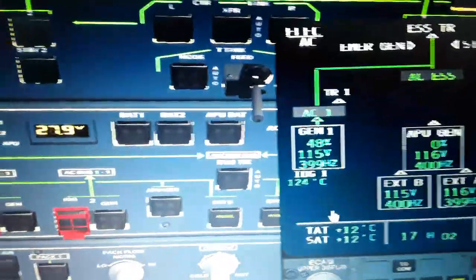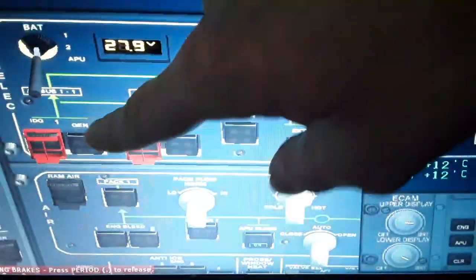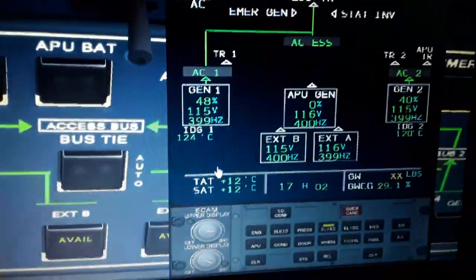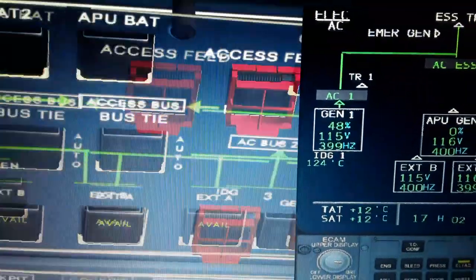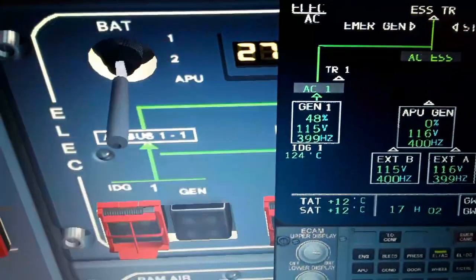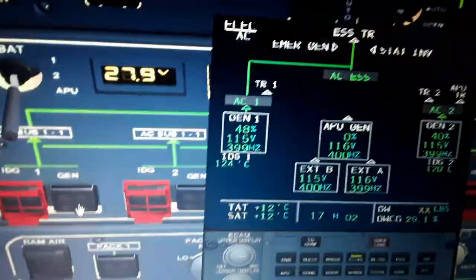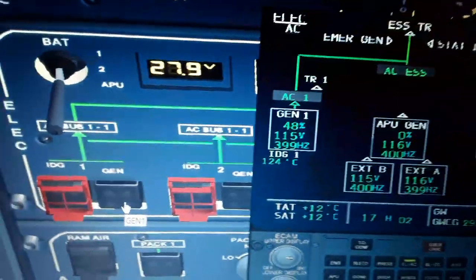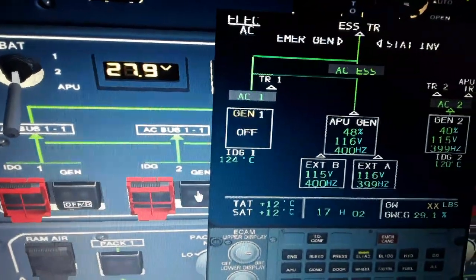We have the electrical alternate current, the left engine and the right engine electrical alternate current. So we have the generator, an integrated drive generator, connected in a small section outside the engine and connected with a shaft through a belt, I think. So we have the contactors here, and the disconnect, the IDG disconnect switches. We should not use them.